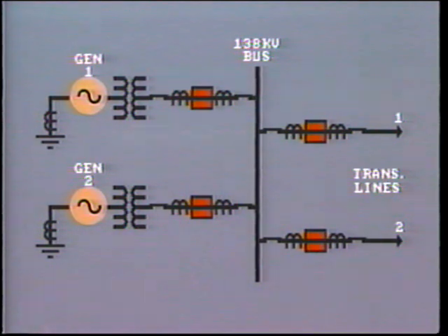To simplify, the following diagrams will show the breaker disconnects in the closed position unless they are normally open. Where a voltage signal is required for protection, say a directional relay or impedance relay, then the VT is normally connected directly to the bus like this.